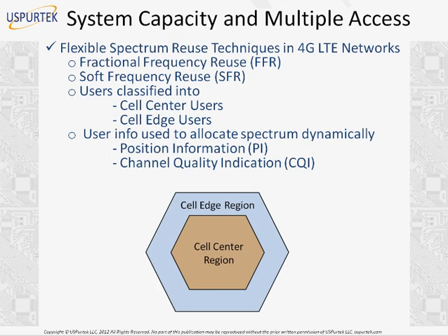Okay, there's a question: near far effect, right? Well, no, this is not the near far effect we discussed earlier. This is definitely in the far field, because we don't do wireless communication within the near field. Near field we use only for measurements in one scenario which I described earlier, just to do antenna measurements. This is not used for digital communication. Any mobile user must be outside the near field. So this is entirely different. Here it's only based on signal strength and signal to interference and noise ratio (SINR), which determines the boundary of the cell center region and the cell edge region, that is, where the signal falls below the threshold where the users cannot get acceptable quality.